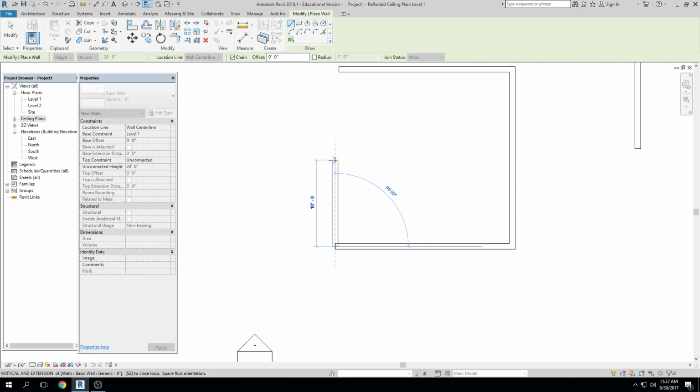Okay, spaces in between everything. Again, it's very hard to get used to that when you've been working in AutoCAD for so long, because you don't use the space bar because it's not a space, it's an enter command in AutoCAD, right? But in Revit, it just gives you space between the specific dimensions. Okay, yep. Can you put 0.5? You can. I'm always worried about bringing that topic up early because I don't want people to get confused on the topic of decimal versus architectural units like AutoCAD has, right? But in Revit, we can do that.